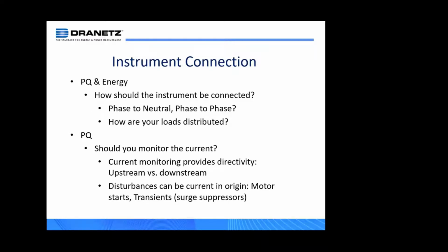This question comes up quite a bit. How should the instrument be connected? Should it be phase to neutral or phase to phase? And usually the answer to that is how are your loads distributed. If your loads are distributed phase to neutral, then the recommendation is to connect the instrument phase to neutral. If your loads are distributed phase to phase, then you want to connect the instrument phase to phase. That's usually the general rule of thumb as far as how to connect the instrument.